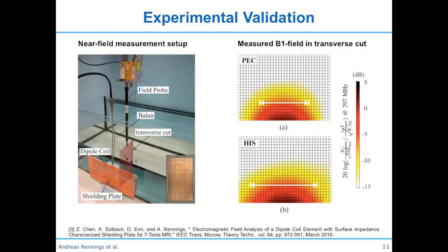Here is the interface to this optical signal, and it's connected to a 3-axis positioner. We use that to move this probe within our phantom. Here you may see this fish tank. It's an aquarium filled with tissue simulating liquid. By using that, we can really measure the electric and magnetic field distributions inside the phantom.